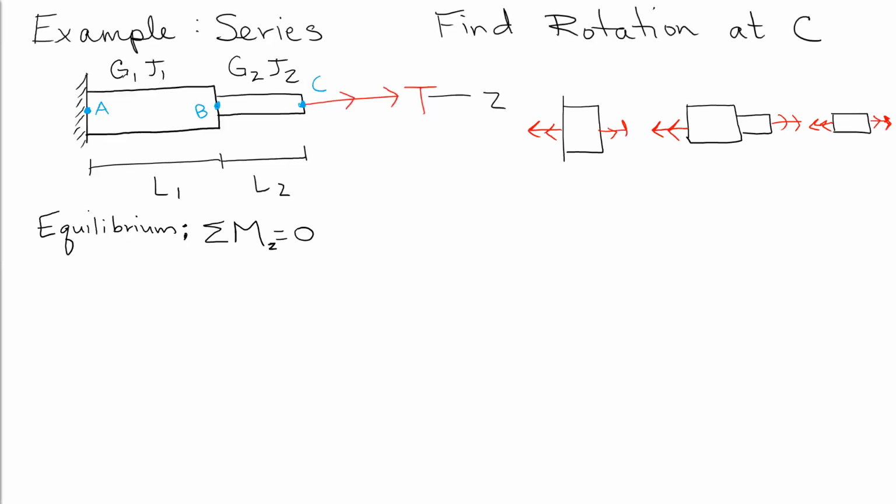So remember we said that this first one and the second one were meaningless because they don't give us any new information. This is the torque applied. I shouldn't say they're meaningless, but this one on the right tells us that torque 2 is equal to the torque. The one on the left tells us that torque 1 is equal to the reaction. So those aren't completely meaningless statements, but they don't relate torque 1 to torque 2. Whereas here in the middle, we see a relationship between torque 1 and torque 2.